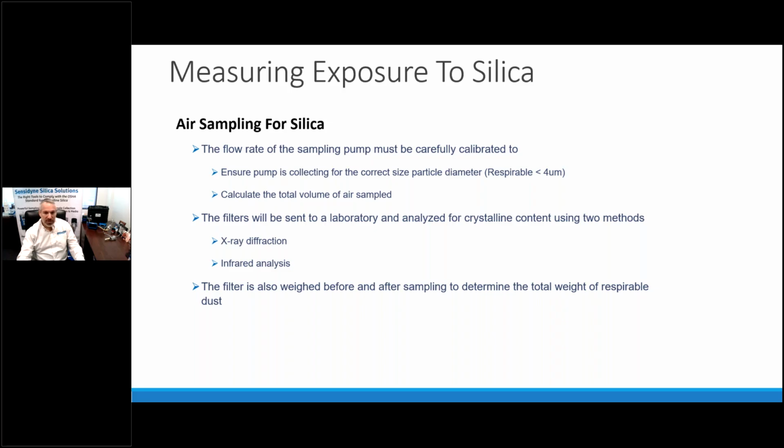The filters are typically analyzed using two main methods. That's X-ray diffraction, also known as XRD, as well as infrared IR analysis. The filter is also weighed before and after sampling to determine the total weight of that respirable dust.